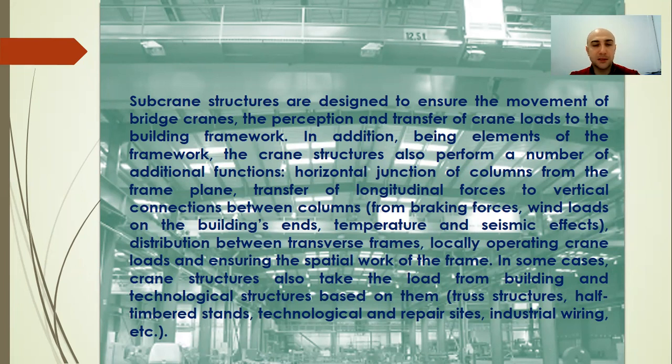The wide beam flange provides reinforcement of the compressed zone and for lateral horizontal crane loads, and also simplifies the fastening of crane rails.